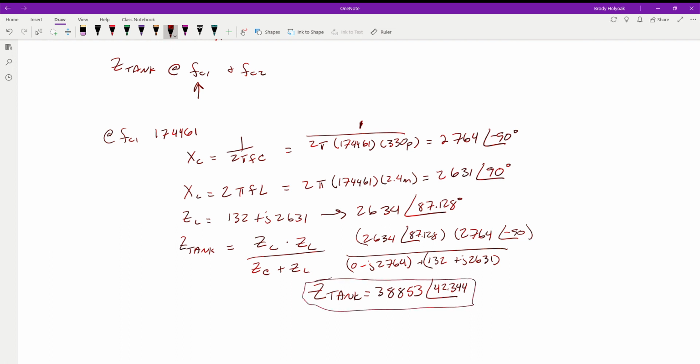This is going to be no different than any of the other filters. That's one of the keys about filters, is that they will always be that -3 dB at the two critical frequencies, upper and lower end, if it's a resonant circuit, or just the one frequency if it's a regular high pass, low pass circuit. So we have this value that we're going to want to plug in for our answer.